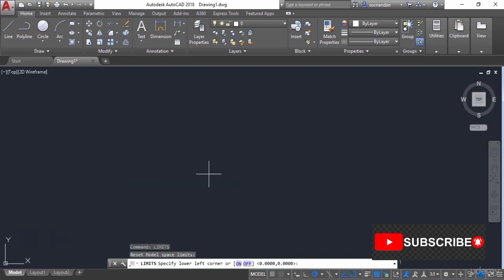Now this will prompt you to specify the lower left corner, which is 0, 0 in this case. So simply type 0, 0, or you can directly press enter because the value in this angle bracket is the default value that will be accepted if you directly press enter. So I'll now press enter, and now you'll notice the upper right corner value, and the upper right corner value is simply the coordinate values of this corner.